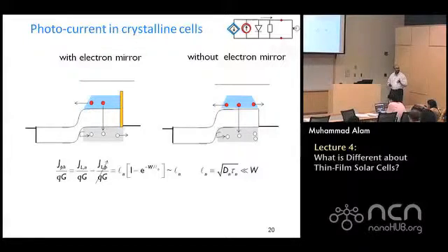Very counterintuitive, why the barrier wouldn't do any good. Again, this formula will tell you why the barrier doesn't do any good. Look at this formula. It simply says that all you have to keep track of is the number of electrons that are getting out through a junction. So I have the electron current moving to the left and the hole current moving to the left. But I have a potential barrier here, it's a PN junction, so my hole current is essentially zero. The amount of electrons that can get out through that contact.